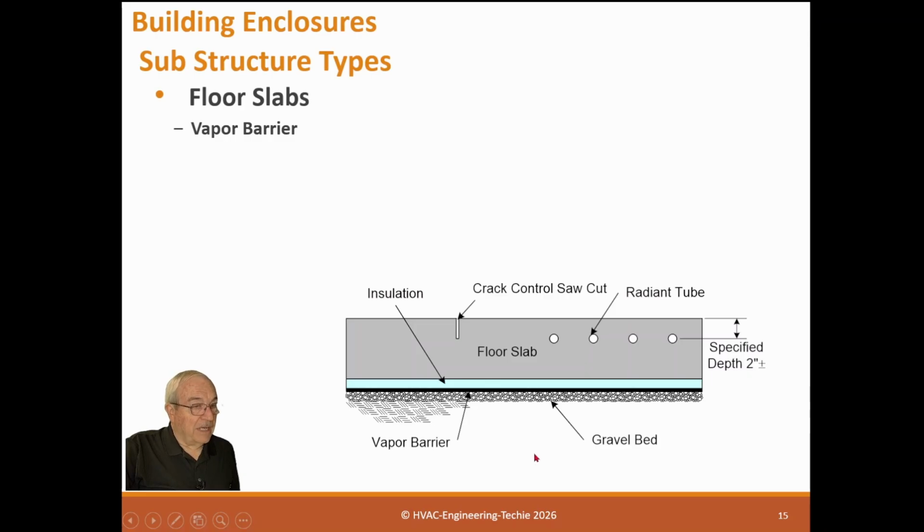Well, hydraulic gradients in the earth are not level. You think of water being like the sea, where the sea has a level. This water in the earth does not. There are different things happening that push the water up or lower it down, and it can be anywhere. So almost all slabs need to have some kind of water barrier and an insulation barrier. So we look at vapor barrier, thermal insulation, expansion joints, contraction, cracking.